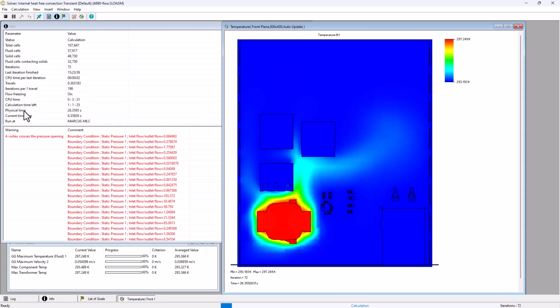And you'll start to see all of a sudden my time step is now from a quarter second up to 3 or even 6 seconds. And that's because of that flow freezing sort of turning on and off depending on what's going on. And as we get further along, you'll see that the current time step trends towards eventually being the saving time step. So if you tell it you want to save it every 10 seconds, your time step will never go above that, which is good. You don't want it to ever go too awful far up.